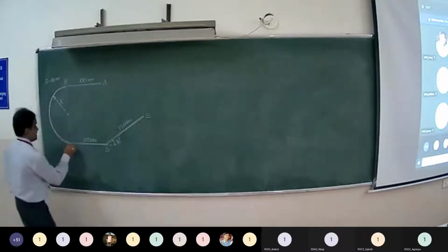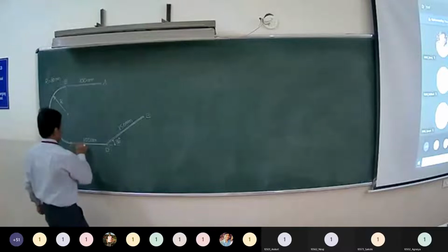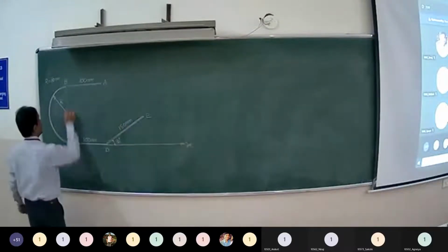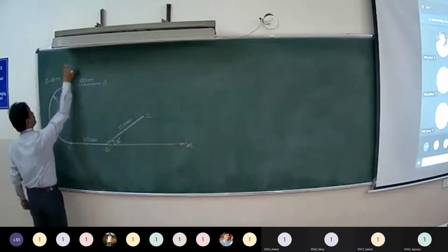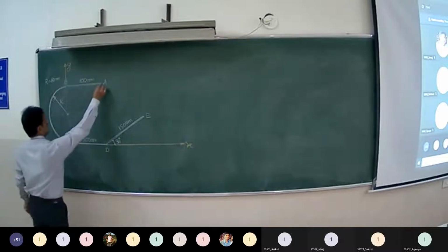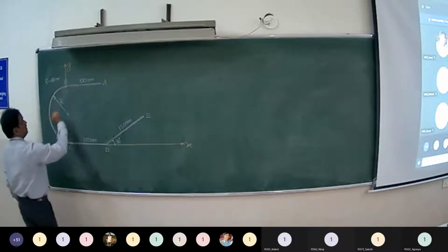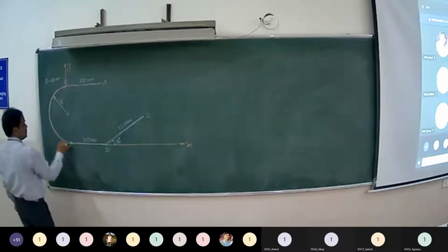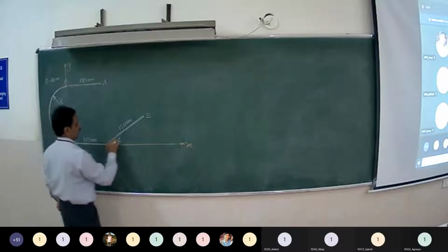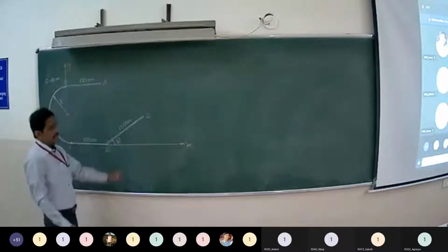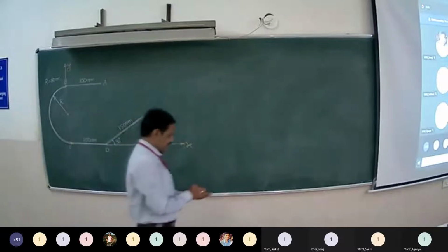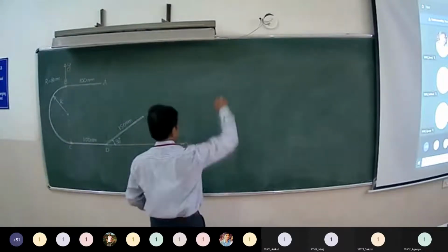So with respect to point C, I am taking x and y axis as the reference axis. And as I said, we are dividing this into line AB, part 1, semicircular arc BC, part 2, line CD, part 3, line DE, part 4. Now, for writing x and y and finding Lx, Ly, we will draw a simple table.